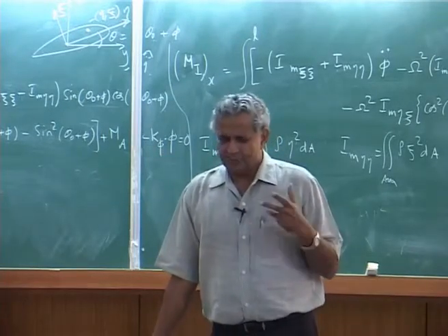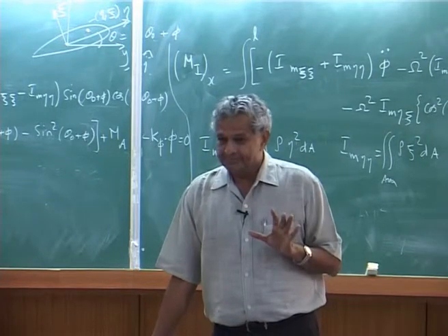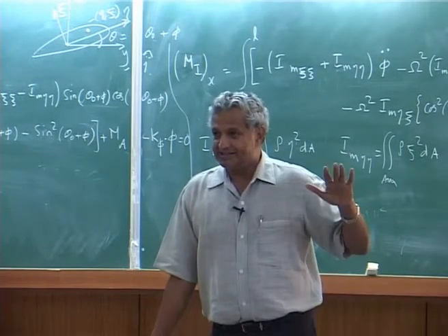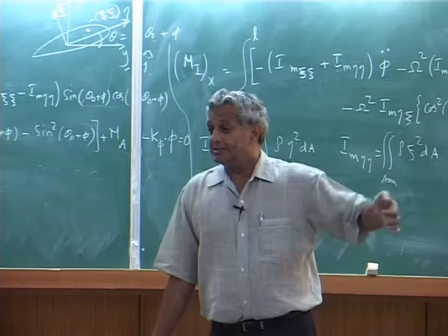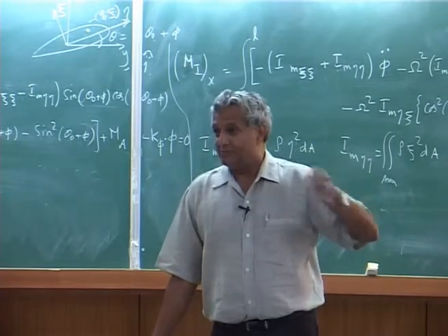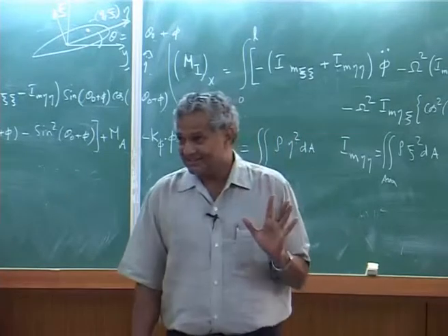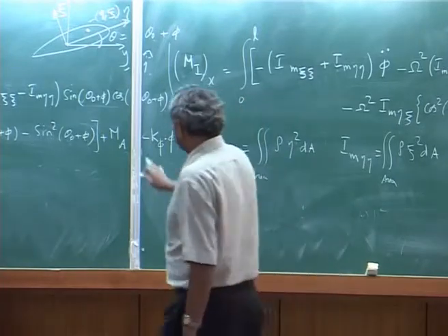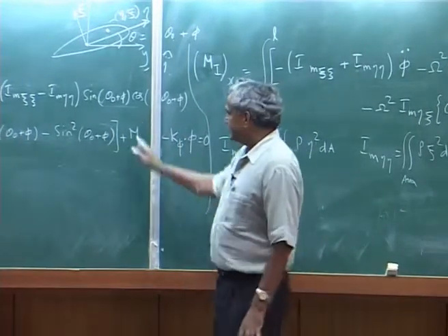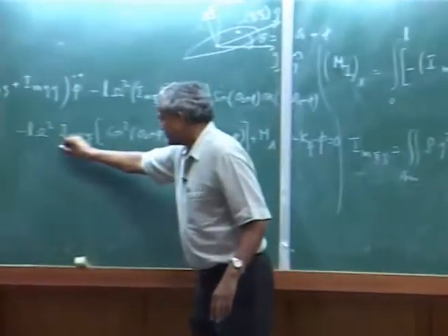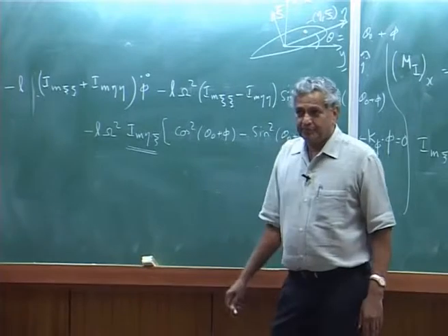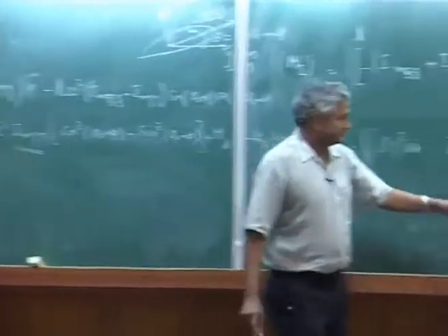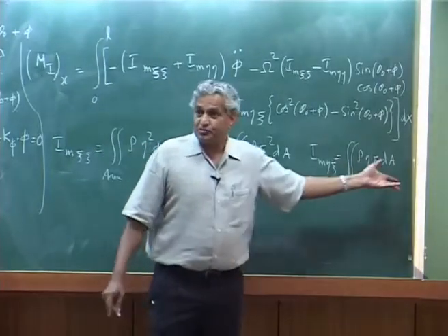Okay, because if you want to be systematic, it's better to start from scratch, so that your fundamental principles are clear: position vector, then velocity, then absolute acceleration of a point which is in a blade which is rotating, then you will not make any mistake. Okay, now if you derive that, this is my equation. Suppose you say my cross section is symmetric, then this term drops out, because I_m eta psi will go to 0.